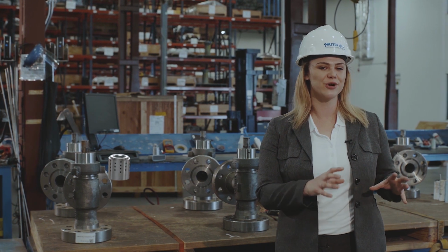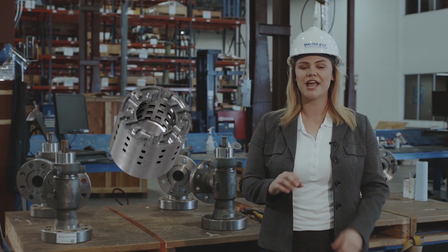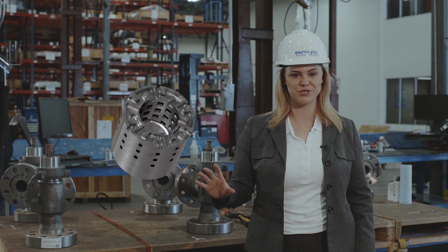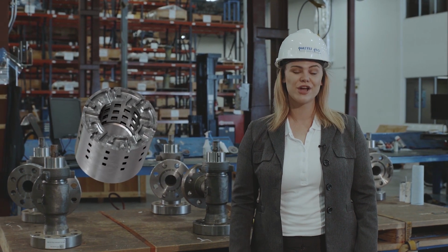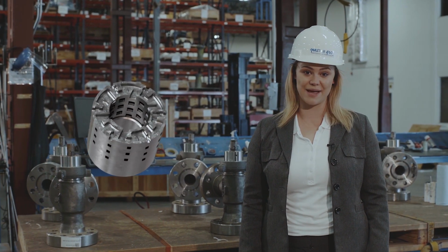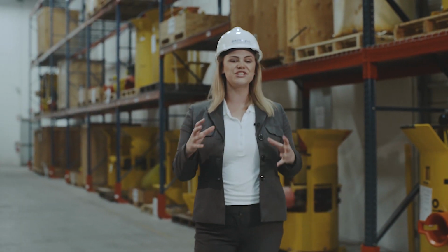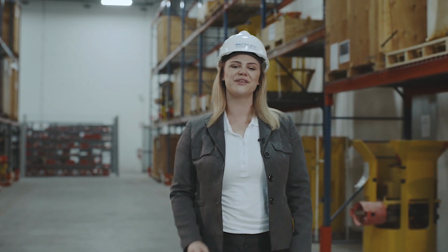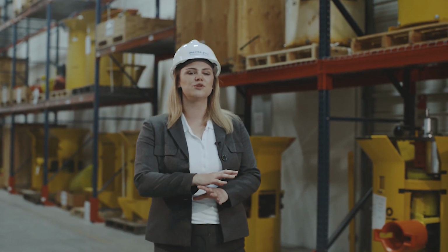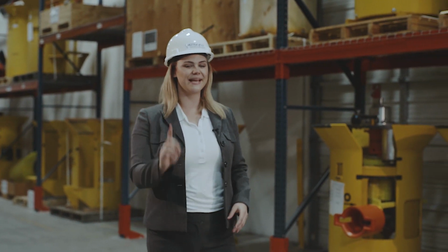It features an internal plug and a labyrinth cage that allows a smooth transition between cage ports. Also, it controls the velocity throughout the labyrinth. These trims are available for liquid, gas, and multi-phase applications. The trim cage is compression loaded and constructed as a solid element of tungsten carbide for durability and ease of service. The custom port designs are available to optimize performance depending on the fluid type and gas-oil ratio.